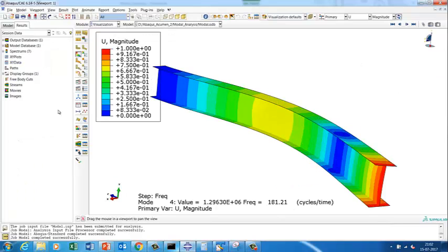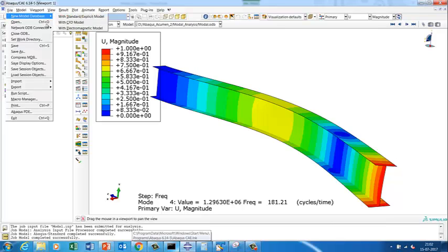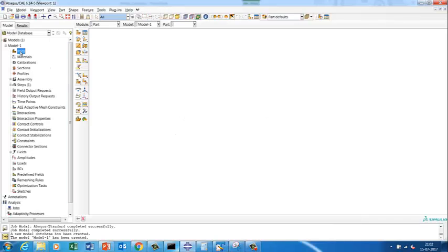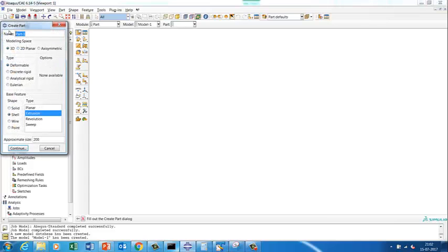So this is exactly what we'll do. Let's create a new model. In Abaqus there are two different methods, Lanczos and subspace. You can get all this information by googling. Subspace is used when you want to extract a minimum number of eigenmodes. Lanczos is more efficient, and we are going to use Lanczos.